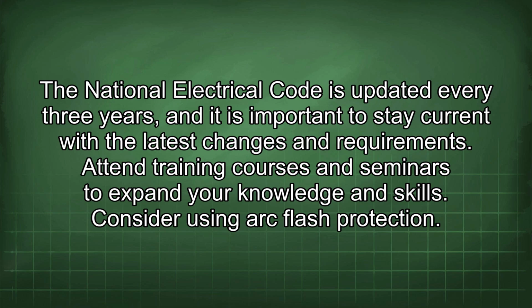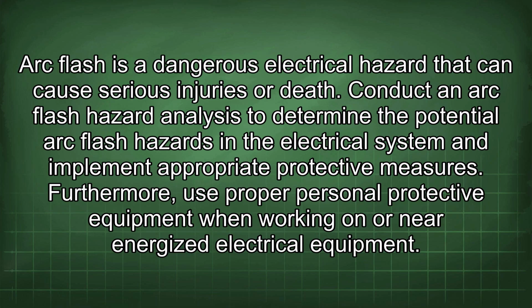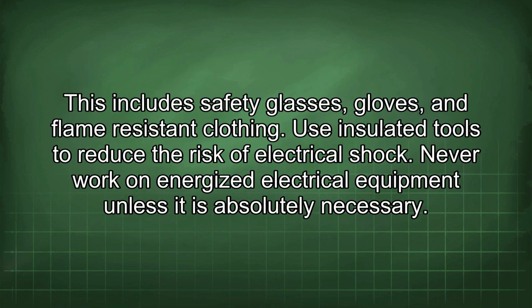Consider using arc flash protection. Arc flash is a dangerous electrical hazard that can cause serious injuries or death. Conduct an arc flash hazard analysis to determine the potential arc flash hazards in the electrical system and implement appropriate protective measures. Furthermore, use proper personal protective equipment when working on or near energized electrical equipment. This includes safety glasses, gloves, and flame-resistant clothing. Use insulated tools to reduce the risk of electrical shock.